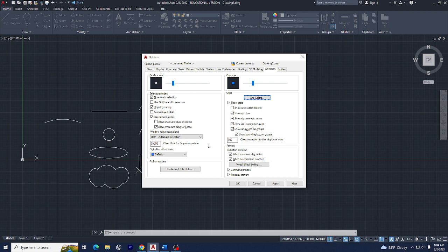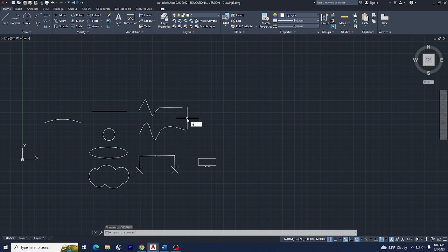All right, there's also a dynamic grip menu, which is grip multifunctional. So type in, let's say apply OK on this. Grip MU, and it comes up again. We've already been there. And that you can change all your multifunctional grips. All right.